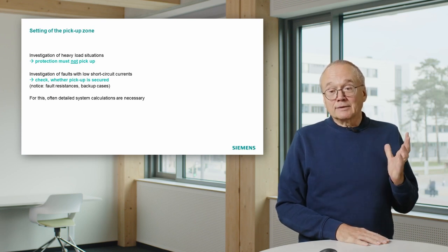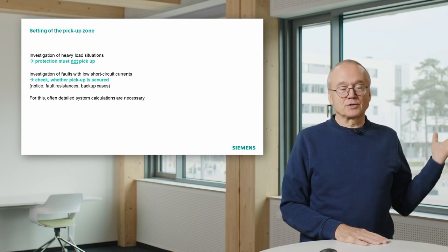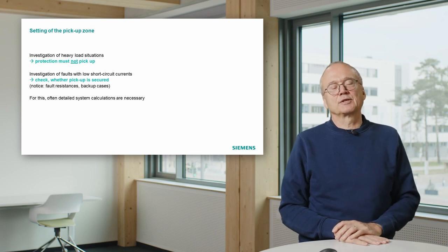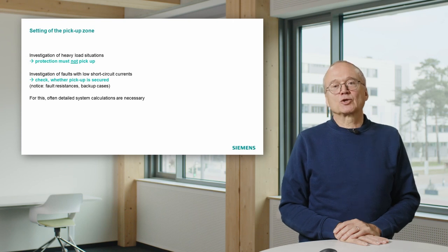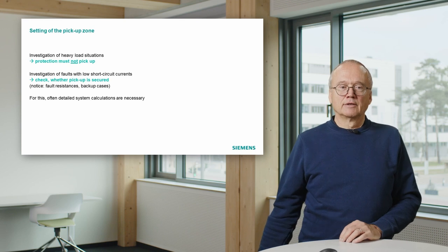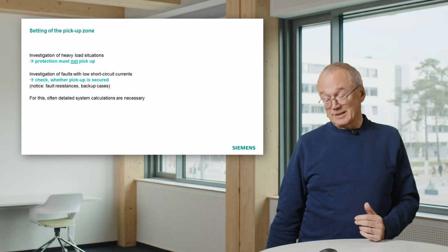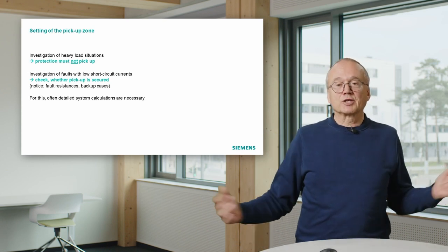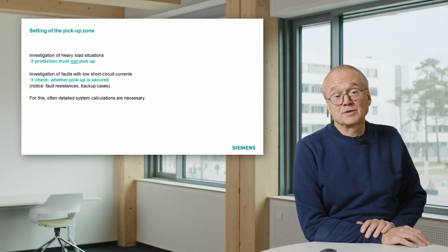But of course, theoretically, you can also have something else. In a distribution system there could be a risk that a tree falls into the line. In transmission it's not so critical. But of course you could theoretically also have a broken wire, for instance in a sub-transmission system, where a wire falls down to earth, and if you have a rocky area or somewhere in the desert, you can have pretty high fault resistances there.